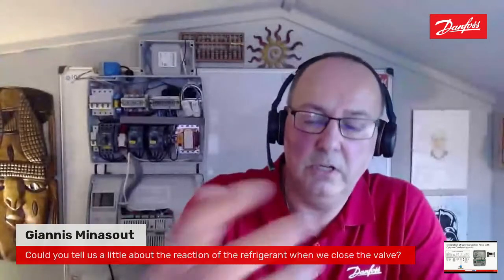Giannis has got a question. Could you tell us a little bit about the reaction of the refrigerant when we close the valve? I guess you're talking about the solenoid valve, Giannis. We close the solenoid valve on the liquid line, and the compressor then acts as a pump, and we basically pump out the liquid down the suction line through the machine, and then into the receiver.